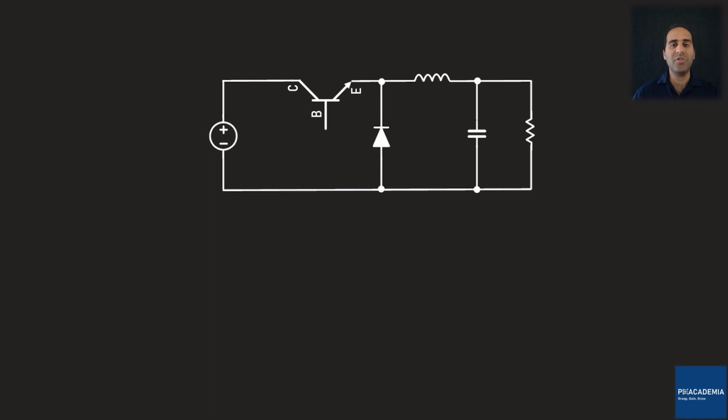Moreover, as a switch, the BJT must operate in the saturation region in the on state, and the current gain in the saturation region is much smaller than the nominal current gain in the active region. Now that all these are set, if I imagine the current gain for this particular BJT is 10 in the saturation region, the base current will be 5 ampere when the BJT is in the on state.